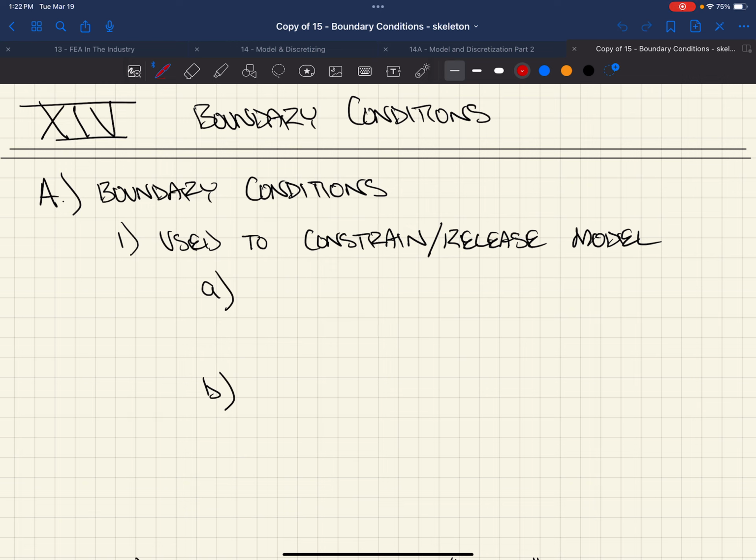And then there's a big tension ring around the entire bottom on top of all the masonry walls. That's stable in VA. If you were to model all those spokes of the wheels and put a vertical load on it, it's stable. But the second that you twist that top ring of members just a little bit, all of a sudden it has no lateral support, and that thing would twist and fall to the ground.